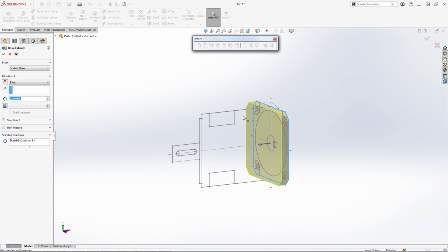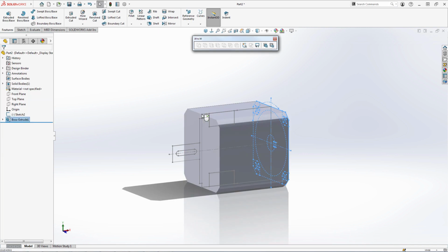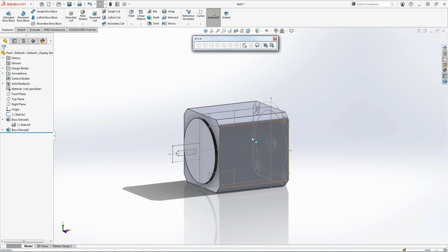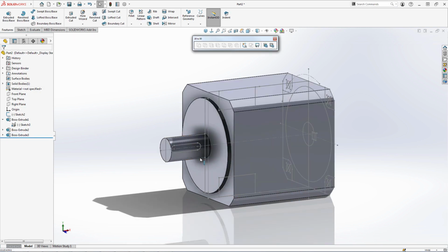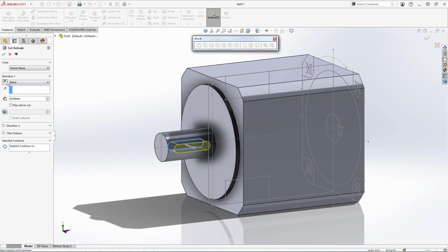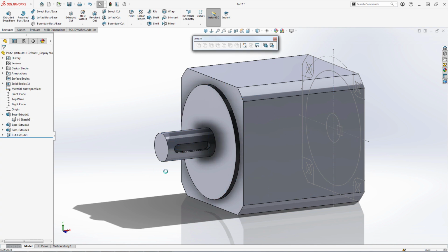From here, we can easily extrude the end sketch and snap to a vertex point to set the depth correctly. Simply selecting a portion of the sketch again, we can repeat the process to extrude another area. The same master sketch can be used again and again, and the intelligent end conditions mean that the 3D model will update dynamically. We can also set intelligent start conditions to specify exactly where each feature starts and ends.